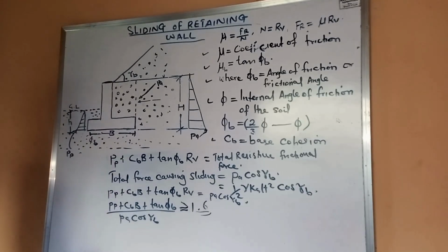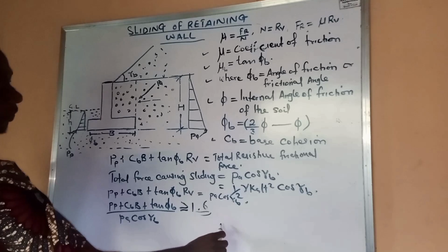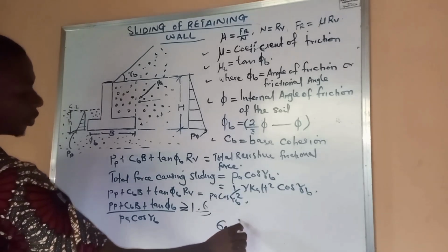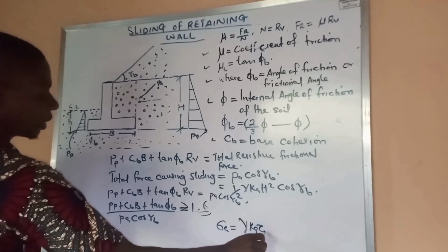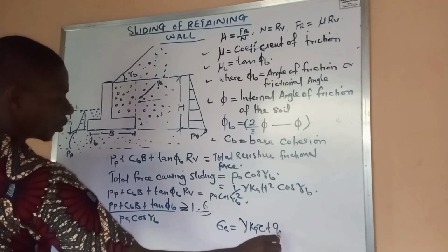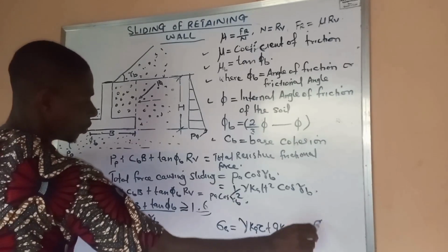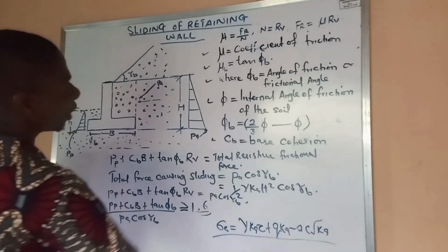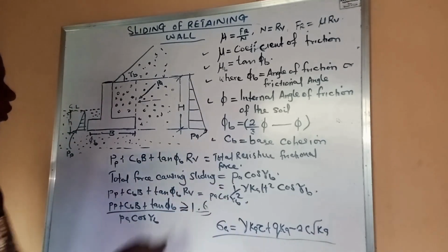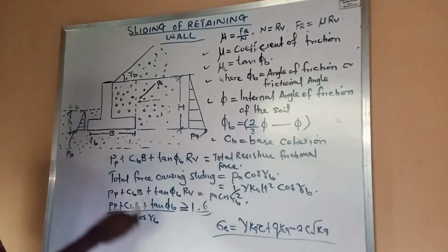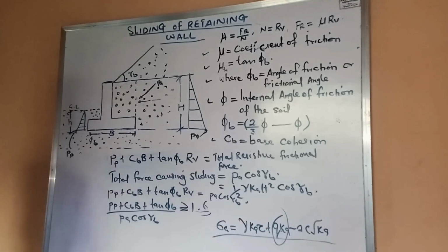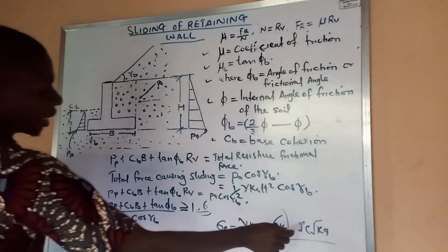All right. Remember that for the active zone, the active pressure has a general formula. We have that formula to be sigma A equal to gamma K A Z plus surcharge load, plus Ka minus 2C root Ka. So this is a general formula for the stress at the active zone. Of course, in this case where we have zero surcharge, the whole of this entity becomes zero. And we are looking at a cohesionless backfill soil, so it means that C here is zero.